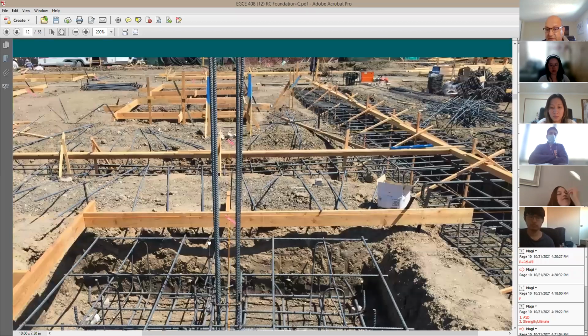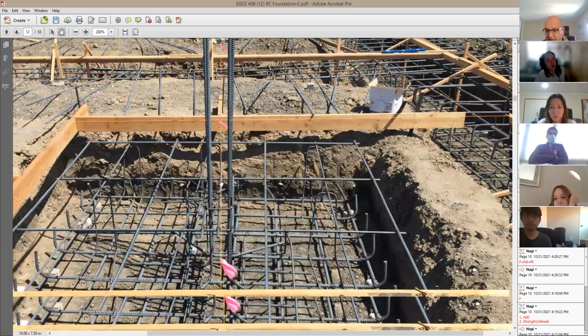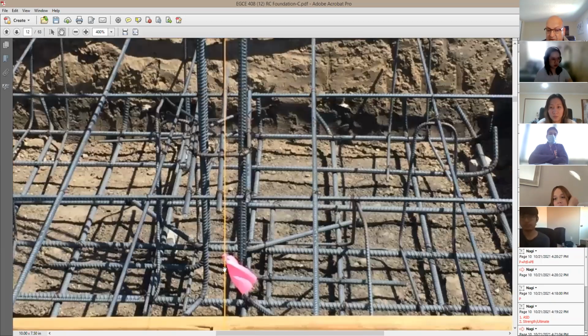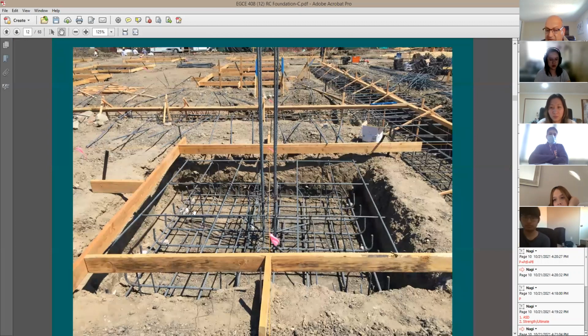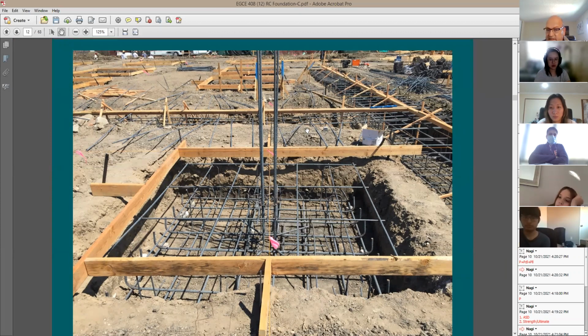You see here the vertical rebars for the column, they're there. You see here the vertical reinforcing, and it goes through the footing, and then in the footing, they bend it this way. So you have this hook, right? They give me enough hook length. So what they do, they're going to fill this hole with some concrete. They just pour the concrete inside. As you see here, the side is extended. I have some wall footing here and some other pads spread in many locations. So, okay, good. So at least now I know how it's going to look like in the site. It's not going to be really actual like a box, but you know what?